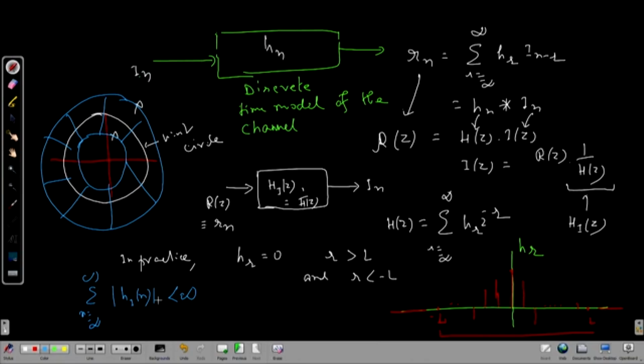So, I am looking for this solution, because you can have HIZ, you can calculate its inverse Z transform for various ROC, region of convergence. One ROC is between these two circles. Here the pole nearest to the unit circle, here the pole nearest to the unit circle, in between there is no pole, take that to be one region of convergence that includes the unit circle. So, if you take the inverse Z transform over this region of convergence, you will get Hin, which will be non-causal, I agree, that is why n from minus infinity to infinity, but it is stable.